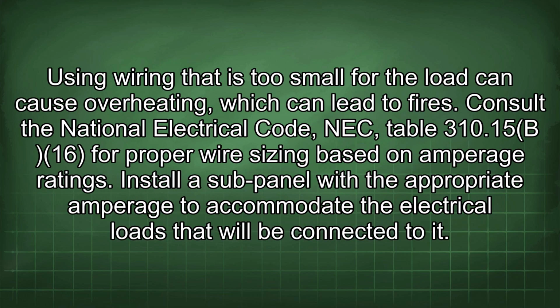Using wiring that is too small for the load can cause overheating, which can lead to fires. Consult the National Electrical Code, NEC, Table 310.15(B)(16) for proper wire sizing based on amperage ratings.